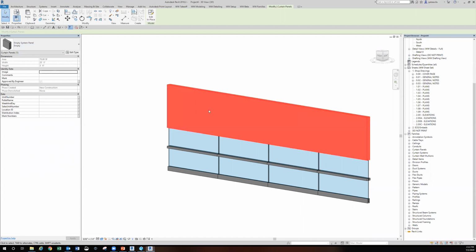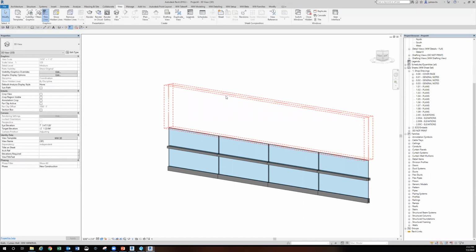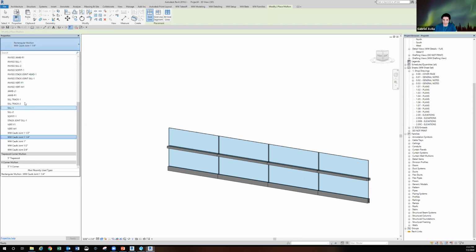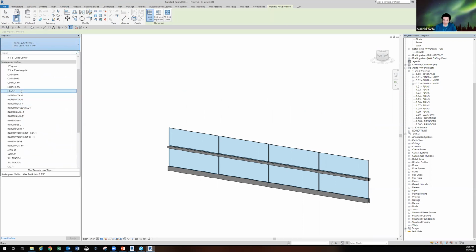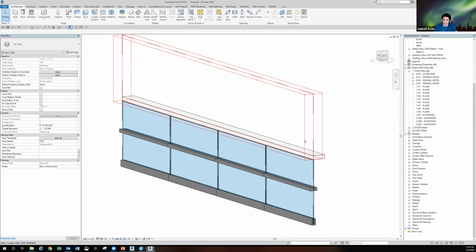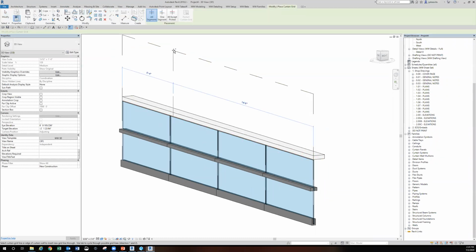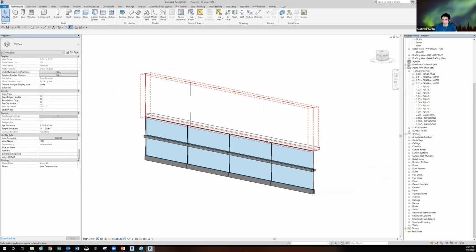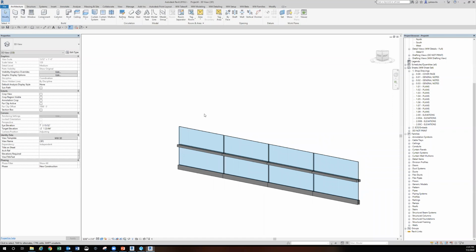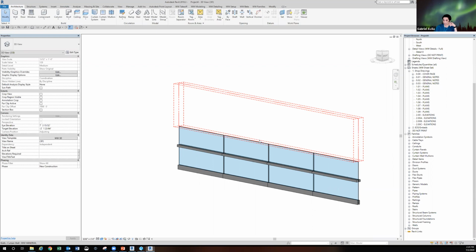And then if you do need joints that are offset from the glass, you can just add in the grid lines for those joints. I'm just gonna put a fake mullion in here, just to show. Something like that, but with the right cap. And you can even do that for the shoe too. If it's a piece that's extruded by us, then we could get that in metal takeoff. There's a couple of things we could do. Good that you brought it up, because I didn't really think about the whole showing the cap over 3 of them.